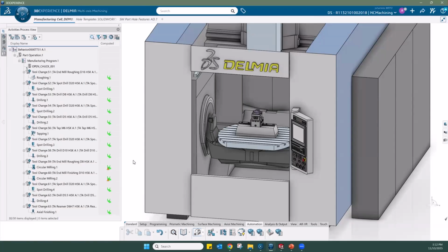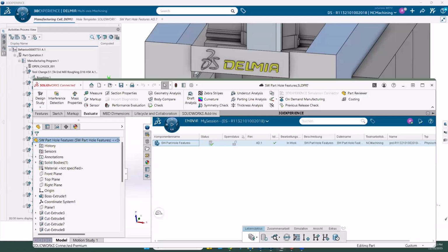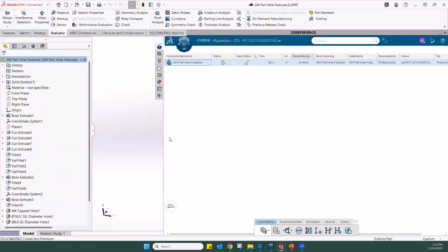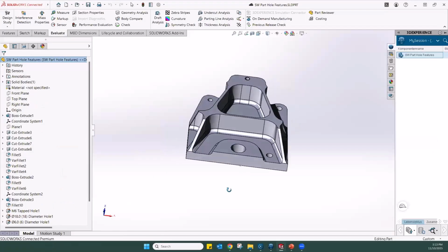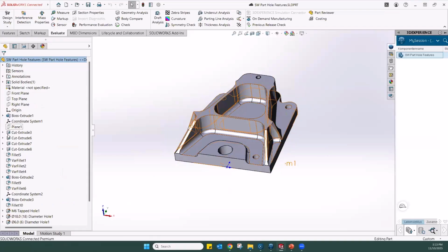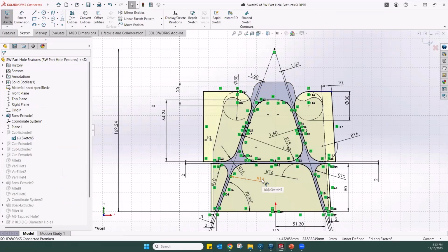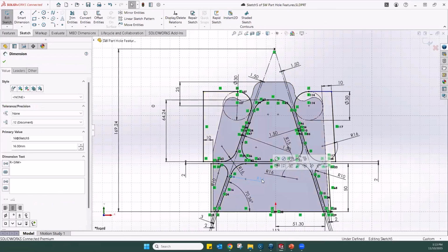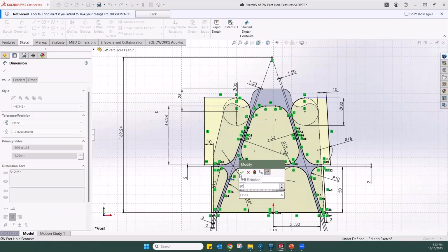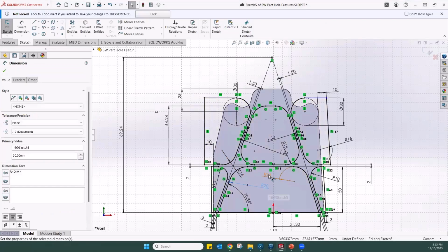Today, we want to see how it works together with SolidWorks if we have a design change with a mostly computed entire machining program. For that, we want to go back to SolidWorks, make it bigger, and change the part. We look where we could change it. We say here in the sketch, open it and change it to 20 millimeters.